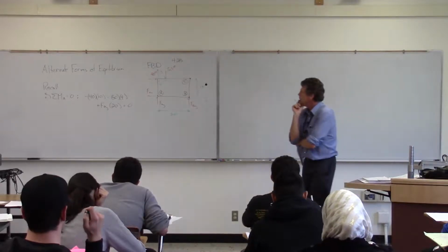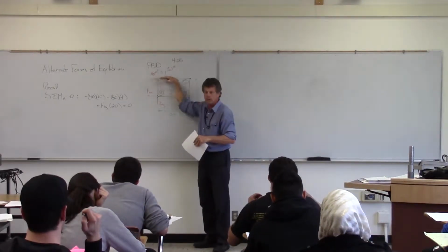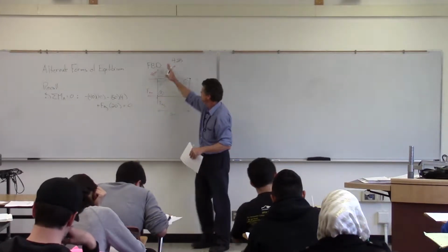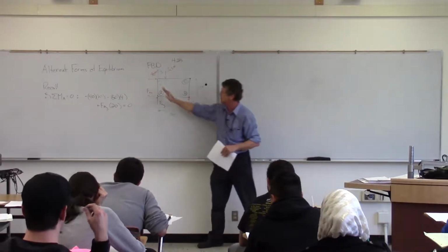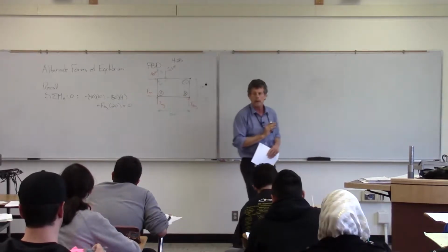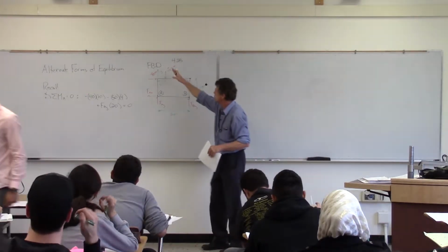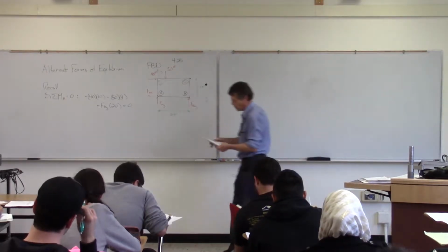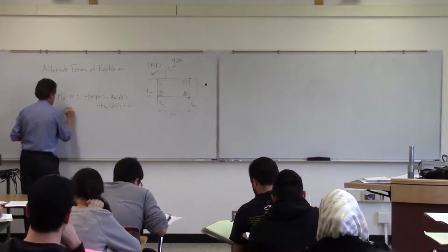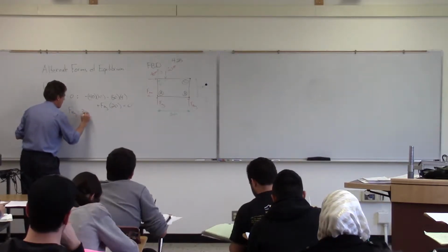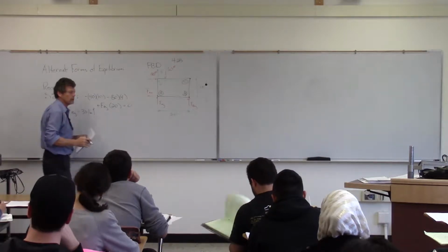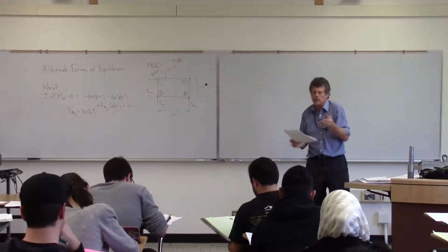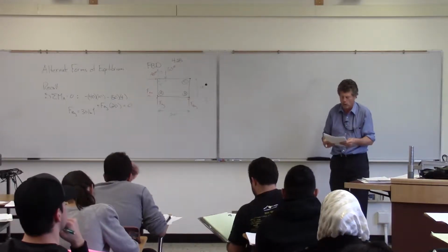Okay, good. So what we did is we took our moment here and realized that this 40 is acting horizontal, but it's got a perpendicular moment arm of 10. And the good eyes here caught that the 50 is merely 4 inches over from the point A in terms of perpendicular distance to the line of action of that force. And then FBY is going to be 20 inches away, so we were able to solve for 30 pounds up by plugging through there. Now, what we did on Tuesday is then we went to sum of forces in x and sum of forces in y.